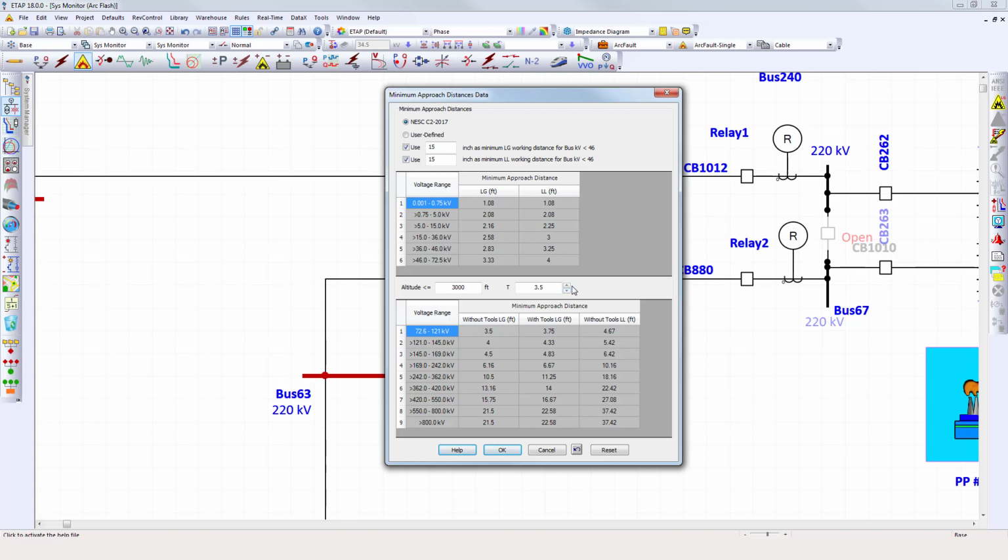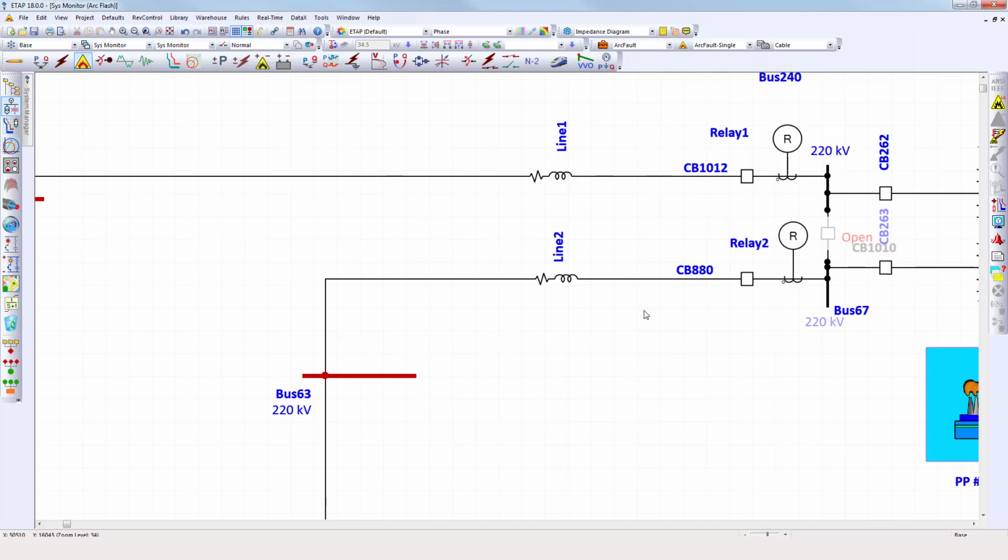Sources of transient over voltage conditions include lightning, the operation of protected devices as loads are added or released from the electrical grid. Once you determine the level of over voltage conditions, you can see that these distances vary. So for lower voltage conditions, the distances are smaller or shorter. Therefore, the typical gaps and working distances will be less, and therefore the energy values will be calculated accordingly.